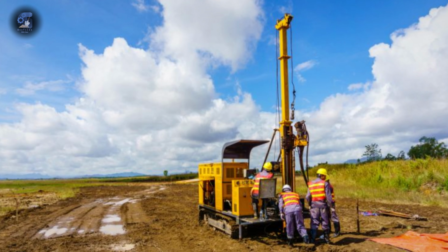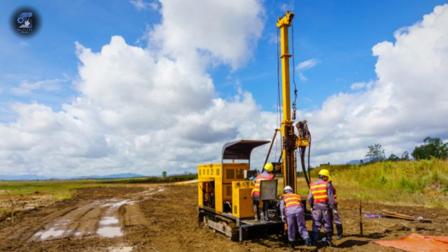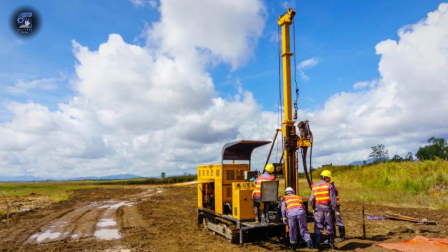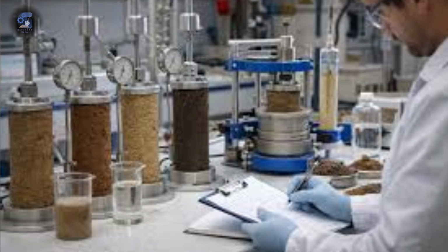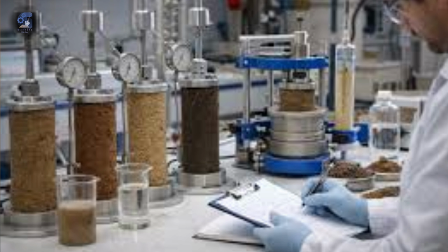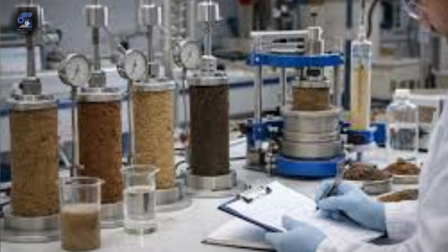To avoid this, there are a couple of ways that geotechnical engineers determine these conditions. There is bore drilling and rock coring using drilling rigs, which come in various shapes and sizes. There is the collection of disturbed and undisturbed samples for laboratory testing to determine the material's physical and mechanical properties. On top of that, there are in situ tests that can be conducted, like the standard penetration test or SPT, the dynamic cone penetration test, and more.